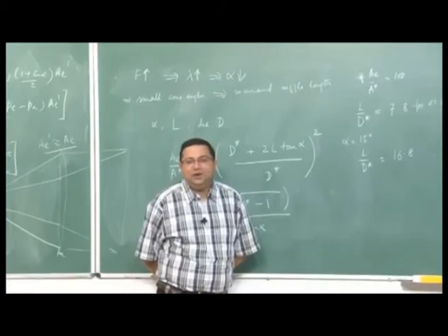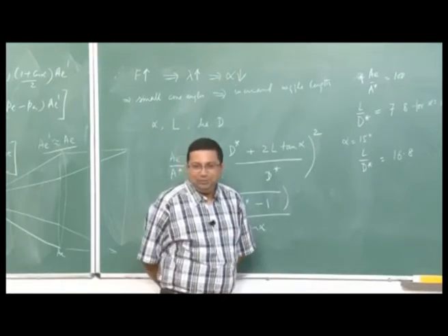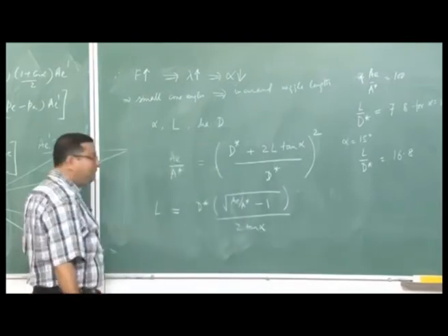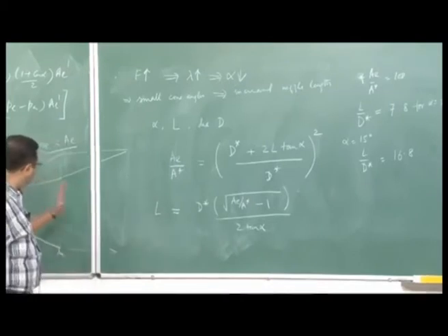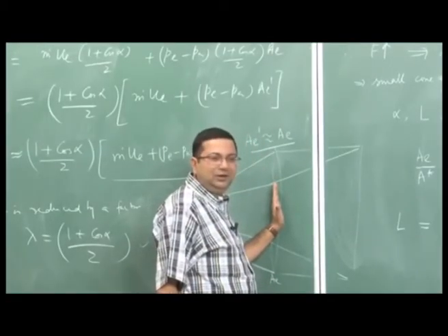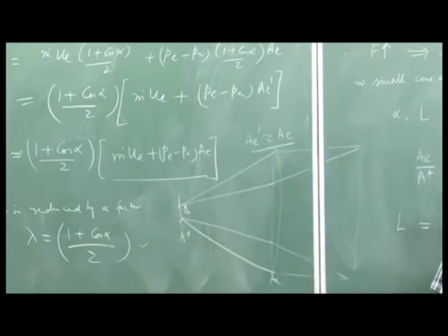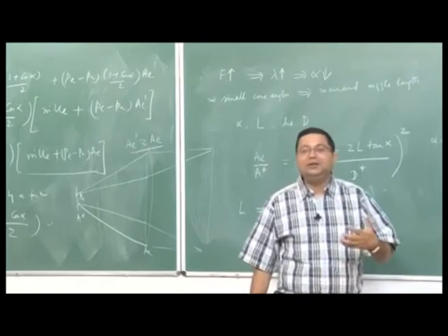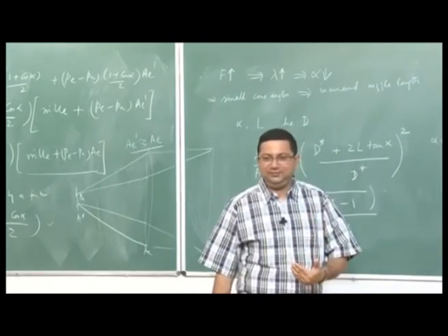The expansion is not going to be complete, we get an under expanded nozzle, right, because this condition A star is for our ideal expansion, design ideal expansion, and we are not truncating it here. So, we get an under expanded nozzle. So, the exit Mach number is going to be less than the design exit Mach number. So, our exit velocity is going to be less, we will be producing less thrust, right.